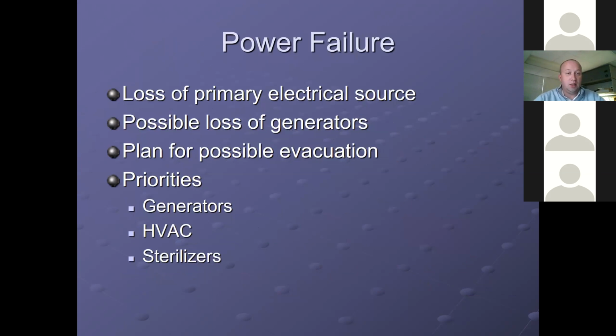We really went into this earlier. If you lose power, you also have the potential to lose a variety of different hazard or life safety pieces of equipment. Generators are key, but in an emergency power infrastructure, you need to understand it's not simply the generator. Almost the more important part is the automatic switchgear. The automatic switchgear cues the generator to come over. It also directs the energy to the circuits you want.